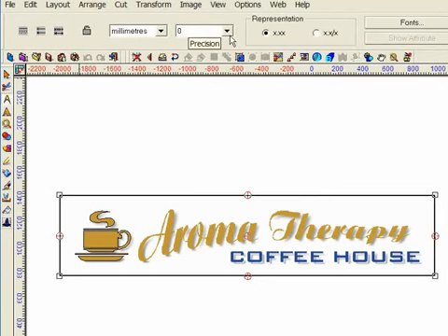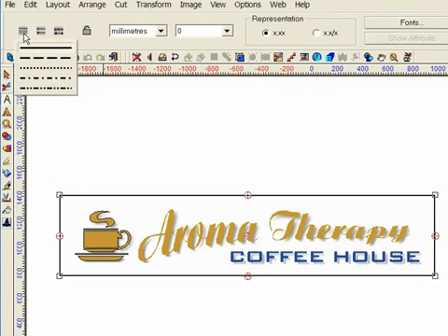There are several options here that can be changed and adjusted to suit your personal preference. Here I can change the style of the lines to be used on the dimensions, and here the type of arrowheads. I want to display the overall width and height of my signage, so I must select the numeric option from this drop down.